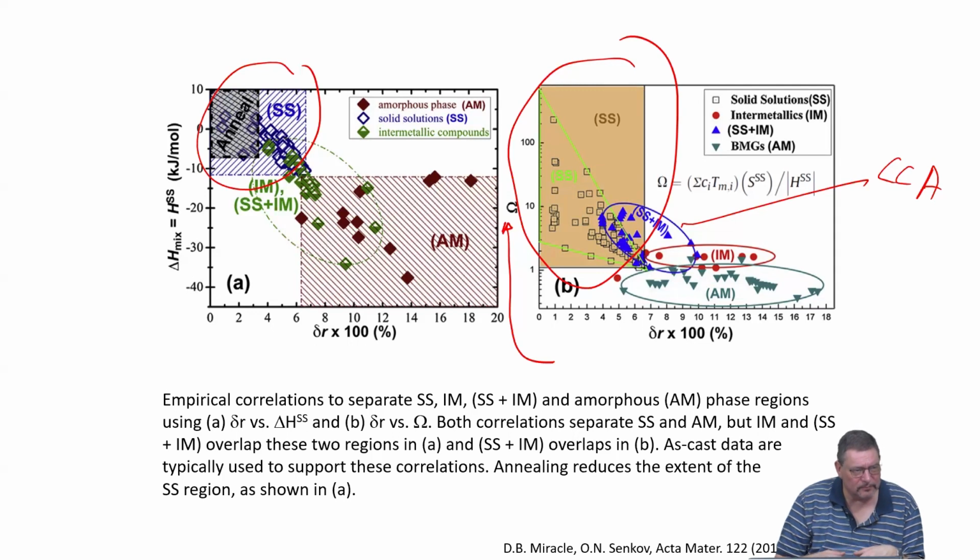Then suppose during printing, during solidification, cracks will form. Yes, that is also a possibility. That is always a possibility. So then you have to change processing conditions. It's not related to the thermodynamics, it's just about intrinsic strains.